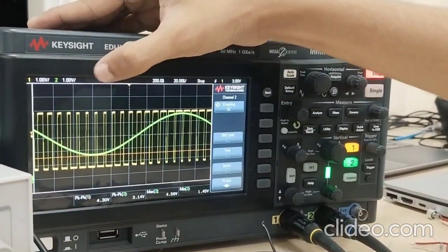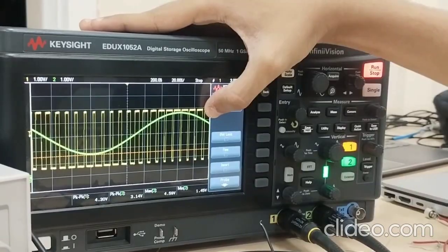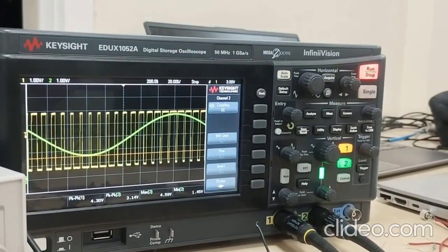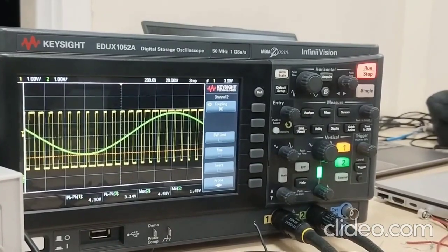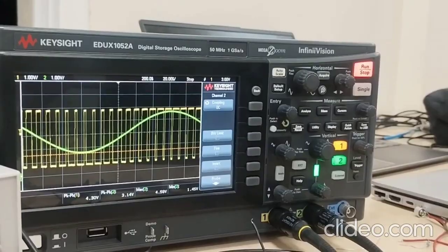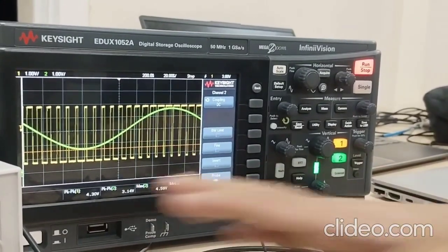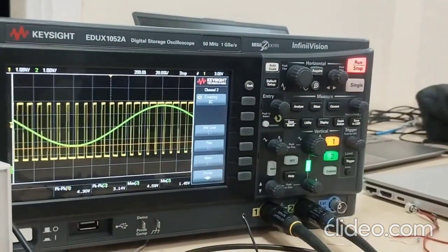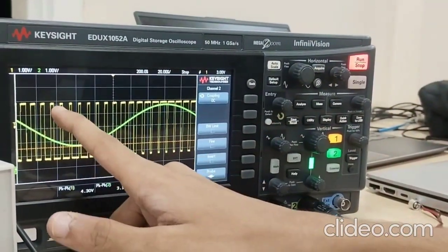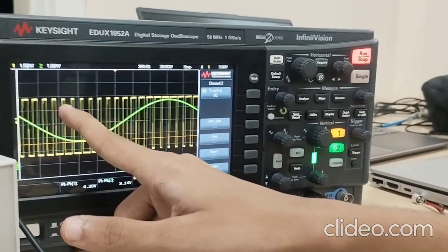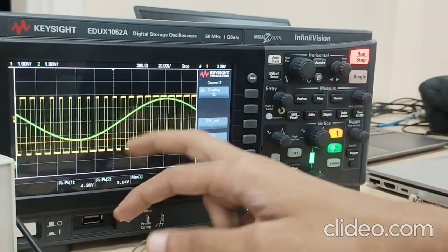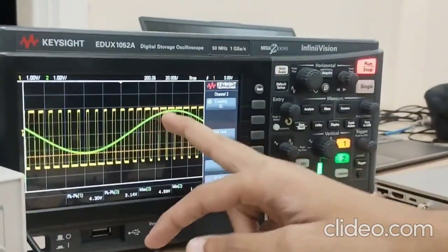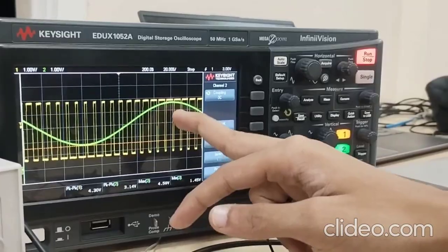The PWM signal modulates the message signal in terms of its duty cycle. Duty cycle is defined as the ratio of the on time and the off time of a digital pulse. So wherever the input is less than the comparator, we see that the duty cycle or the on time has decreased. On the other hand, wherever the message signal amplitude is higher, the duty cycle is more.